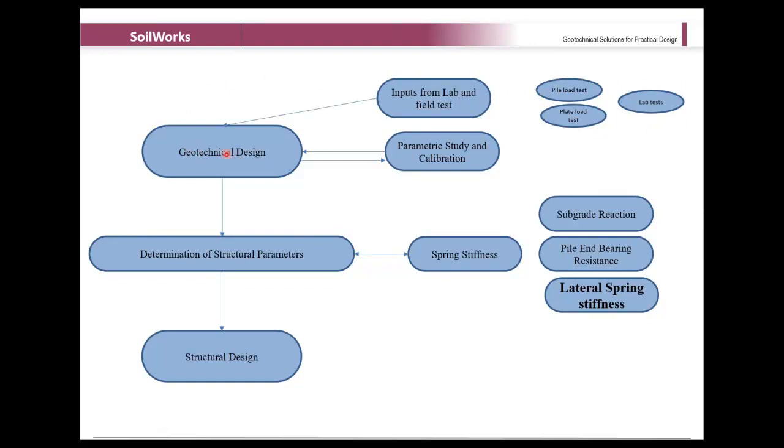And then this geotechnical engineer, based on the load, the soil profile, and the lab and field test data, does some parametric study and calibrates your numerical model with the existing data, so that he can come to a particular geotechnical design. So geotechnical design includes the type of foundations, dimensions of your foundations, the spacing of piles in case of deep foundations, the diameter of the piles, everything. So this is the basic input a geotechnical engineer can provide to a structural engineer.